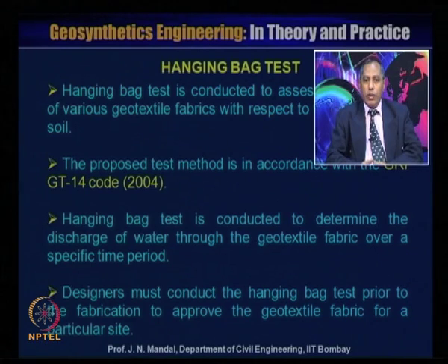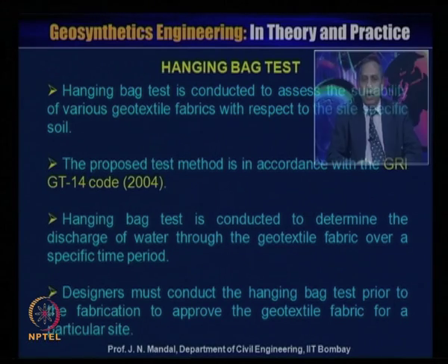The designer must conduct the hanging bag test prior to fabrication to approve the geotextile fabric for a particular site. It is not so easy: knowing only the apparent opening size of the geotextile is not enough to satisfy this criterion, and it is recommended that one should also proceed for the hanging bag test. This is very important for the selection of the proper kind of geotextile tube.